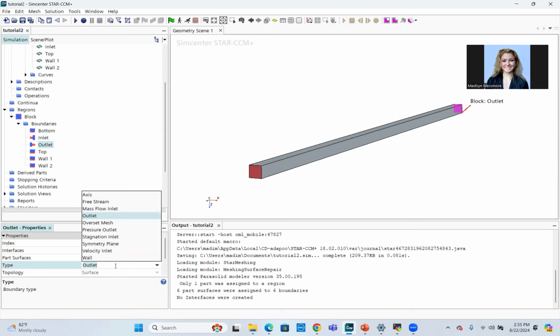Something that's important to know is, we saw those Navier-Stokes equations, and they have a whole bunch of variables. Well, effectively how this works is you're saying, okay, I'm giving you all of my boundaries. I know some quantity where the flow is coming in, whether that be your mass flow, the velocity of the flow, whatever, some property of your fluid at the inlet where it's coming in. And you also know some property where it's coming out. You can have multiple outlets. You can also have multiple inlets.